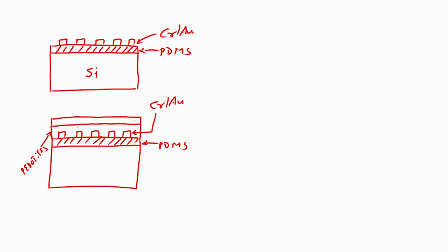So we have photoresist spin coat, and this photoresist is again a positive photoresist. After spin coating the positive photoresist, the next step is soft bake at 90 degrees for 1 minute on a hot plate, followed by the mask. You load the mask and then you form the piezoresistor.